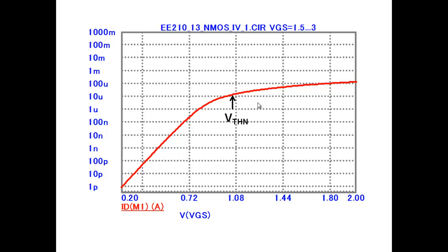If I simply scale it, let's say VTN is 1 when the range is 2, and I make VTN equal to 0.5. I scale VTN to 0.5 here, and the shape of the characteristics remains the same. As I go from VTN 1 to 0.5, the curve will shift like this. And what will happen to the leakage? Leakage will increase.